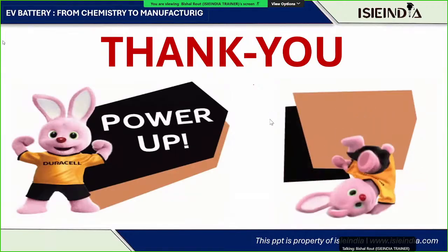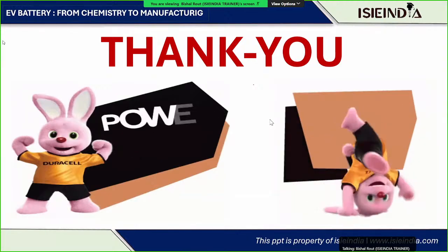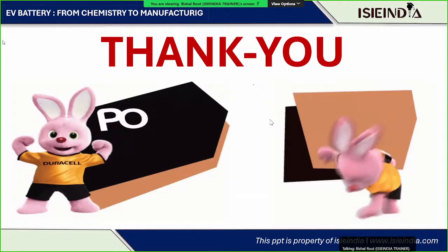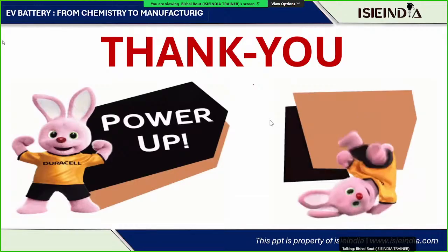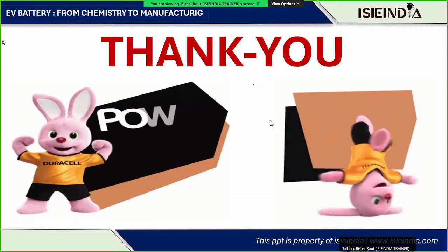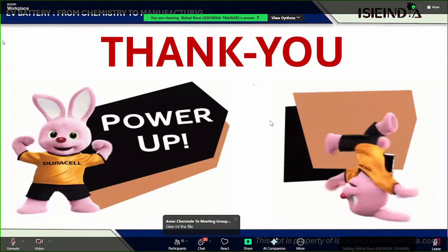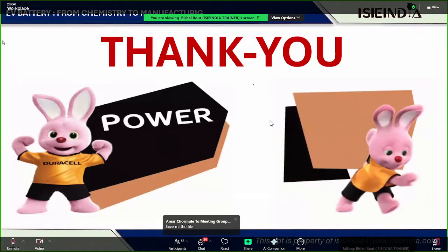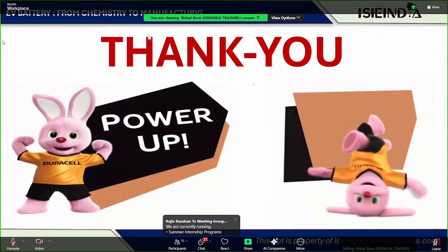Then they will perform the isolation resistance test as well. This is one of the most important high voltage safety tests. This test checks the isolation between the high voltage battery terminals and the vehicle chassis body. Poor isolation can cause electric shock, leakage current, insulation breakdown, and high voltage safety hazards. The system measures insulation resistance, typically in megaohms, and the instrument used is called a Megger. So a Megger is used to measure this.